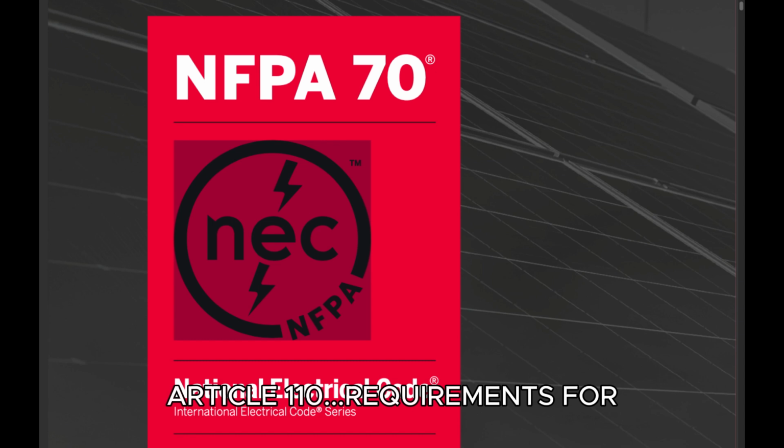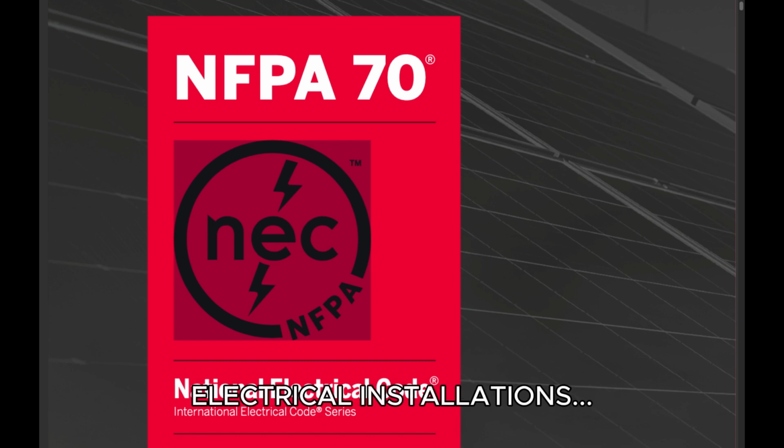Article 110, Requirements for Electrical Installations. Part I, General. 110.1 Scope. This article covers general requirements for the examination and approval, installation and use, access to and spaces about electrical conductors and equipment, enclosures intended for personnel entry, and tunnel installations. Informational note: See Informative Annex J for information regarding ADA accessibility design.